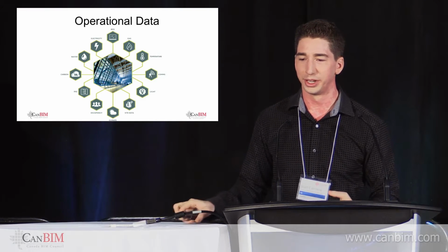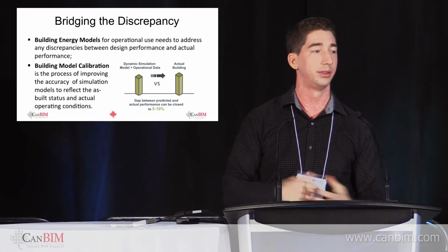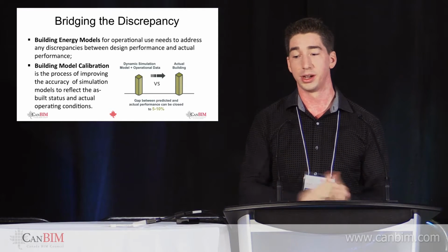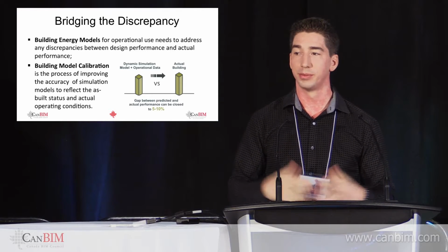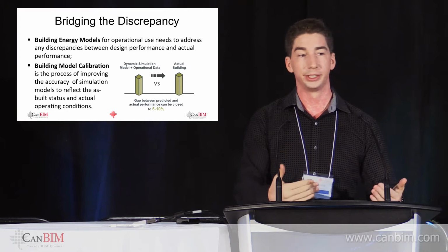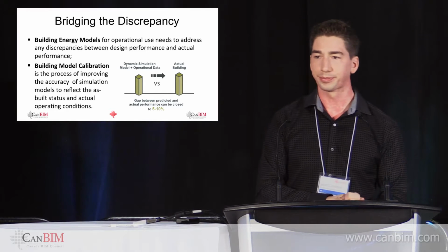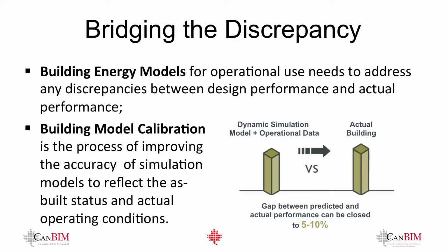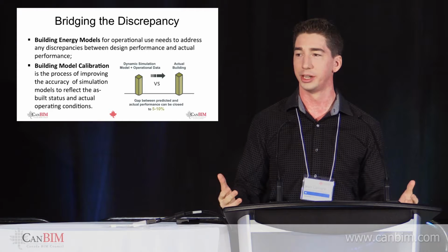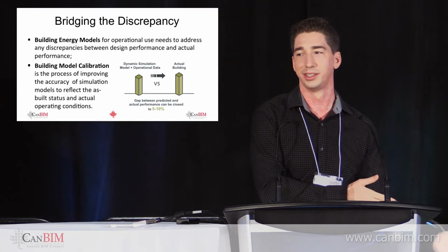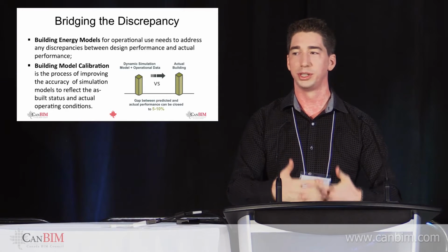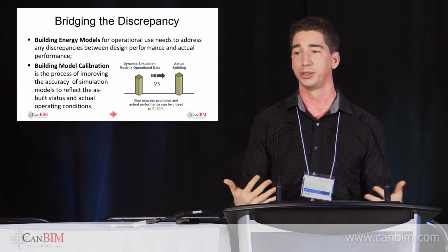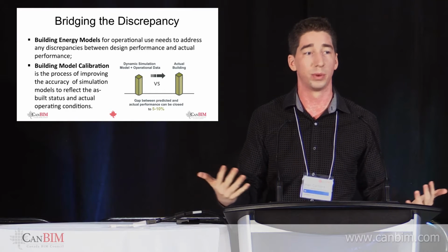So we're bringing in sensors, and we're using this to bridge the performance gap. We're going to go from a compliance model, the model that we've done for LEED compliance or code compliance, which is just based on assumptions. We're just saying the building's going to be operated from 8 to 5, which is good enough. But maybe we showed up here at 6 in the morning. Might be a little bit different. So our proposed model is usually an assumption, and it's never going to be accurate. It's always going to be 5–10% off because inherently it's supposed to be.